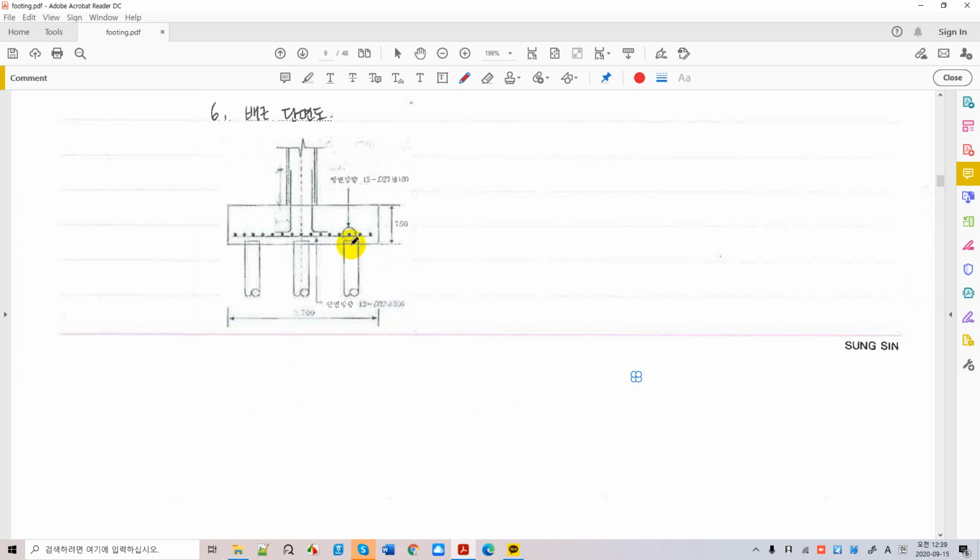So next, very clearly, we're going to take a look at the pile load test. There are two ways for a pile load test. The first way is a static load test, right? And the other way is a dynamic load test. The static load test and dynamic load test are tests that you need to make sure your piles can be supported by the soil with the allowable pile bearing capacities.